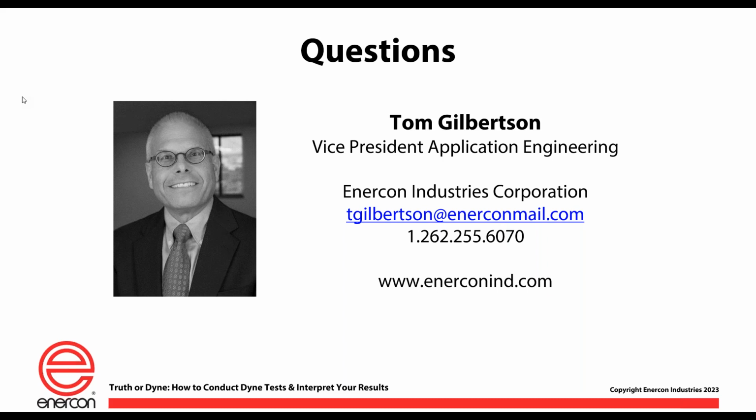If you see things like that, maybe that's a sign of overtreatment. So go back and look at the process, and make sure that everybody's operating in the process conditions that you want them to. And all of these power supplies for corona treaters are variable. If you see that, turn the power down. That's a simple answer here. But yeah, I can pick a handful of times over all these years where I've actually witnessed overtreatment causing a poor adhesion profile. It's possible, but it's not normal. It's not sort of a daily thing that you'd have to look at.